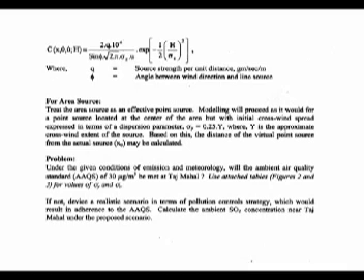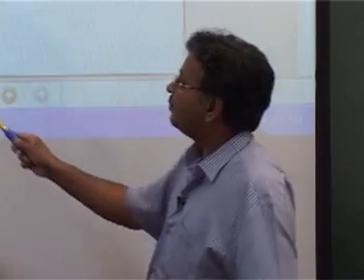You remember we said sigma y was the distance of the area source divided by 4.2. For that you can take 0.25, where y is the approximate crosswind extent of the source. Based on this, the distance of the virtual point source from the actual source, x naught, may be calculated, that we discussed.